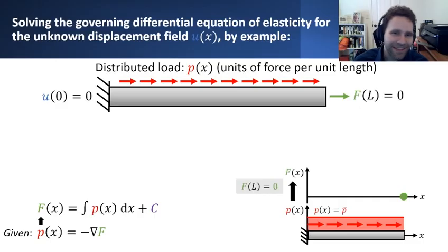So if this distributed load is constant, uniformly distributed over the entire length of this axial member, then we can plot that and show that it looks like some constant function that has uniform value all along the length. Now, given our steps of how we related different quantities to one another, the governing differential equation of force equilibrium gave us a differential relationship between this axial distributed load P and how the internal force F, also a function of position potentially along the entire length, varied.